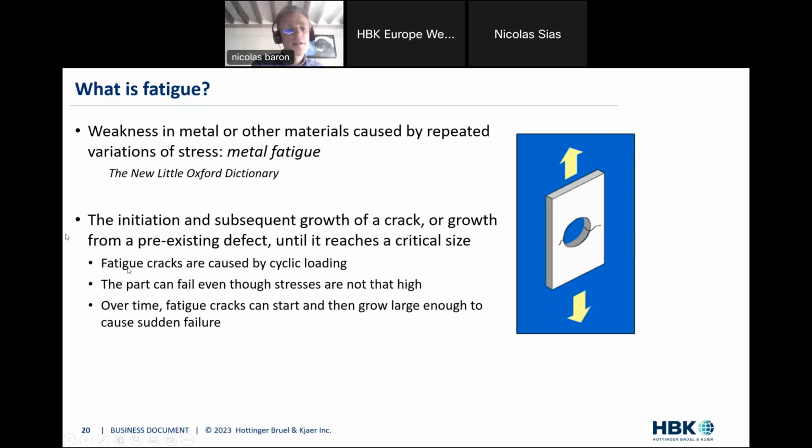Just to reiterate, because this is very important, if there is one key message you must take away from today's seminar, if you're a beginner, it is the fact that fatigue cracks are caused by cyclic loading. So we really want a variation of the stress acting on our design. That's one thing. Second, another important thing is that the part can fail even though the stress values are not really high, and that's key in fatigue also. You don't need a big load, a big impact, a big force to create the fracture. Fatigue is not about that at all. Fatigue is really the repetition of cycles at maybe a rather low value, but it's the repetition that will create the fatigue. So that is the definition of fatigue.